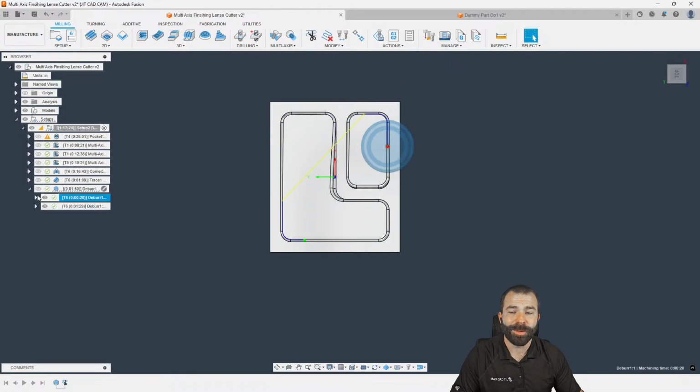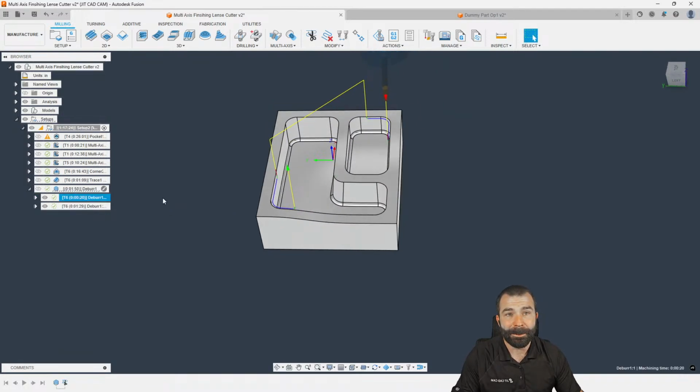And what this is now going to do is split my toolpath as if I was going to move my clamps after the first part, right? So this is, again, to me, toolpath trimming is insane. It's super neat if you have to deal with clamps or things in your way, or you only want to machine one area of a part. You have that ability inside of Fusion.